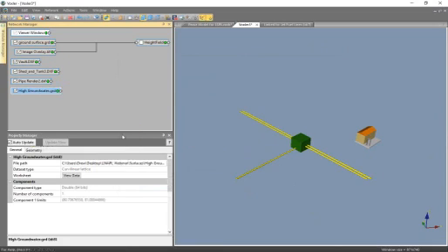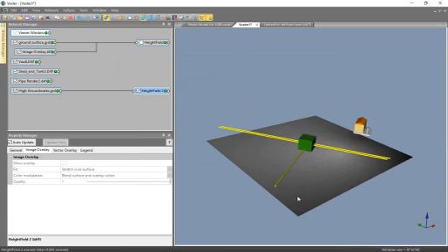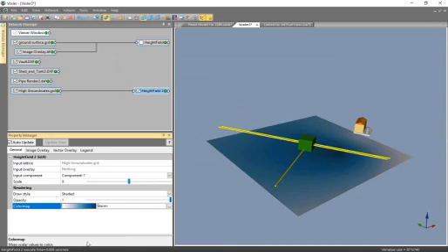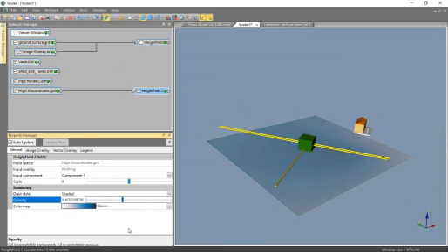And again, we can render this with a 3D surface or a height field. I'm going to change the color map just a little bit. And I'm going to reduce that opacity to about 40% or so.